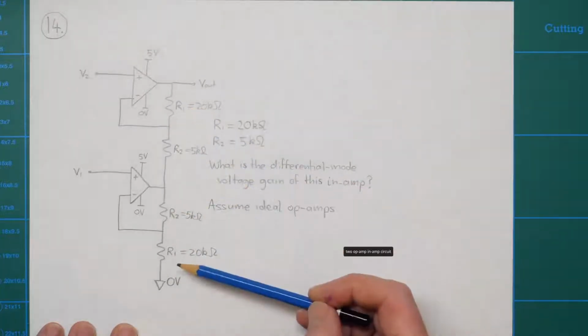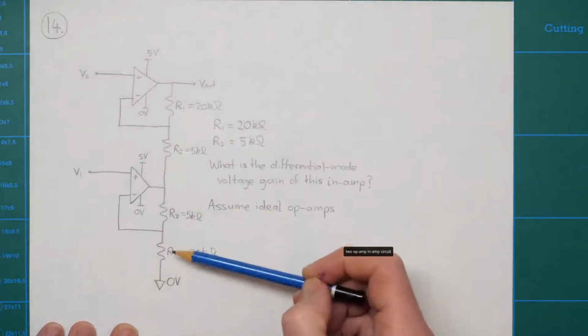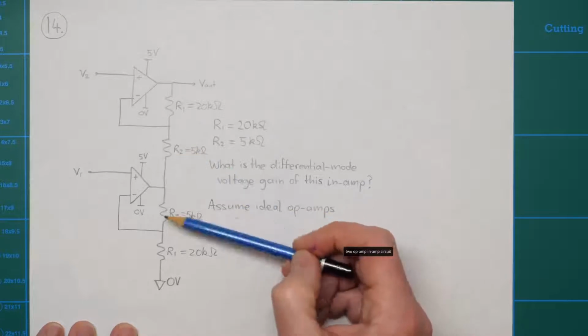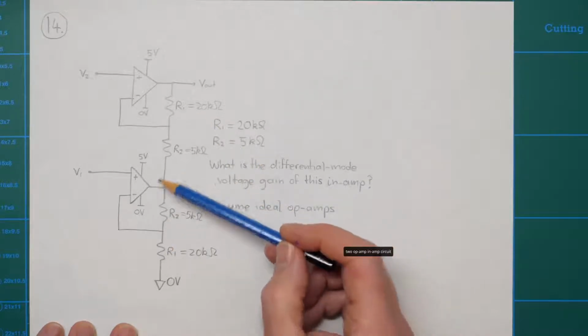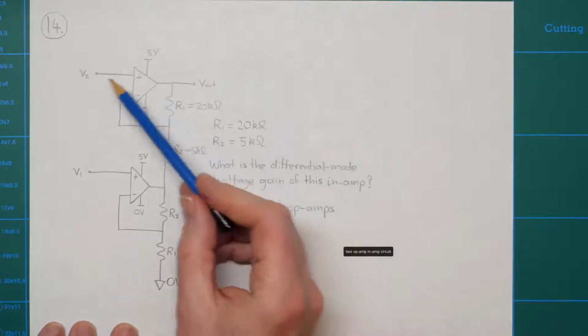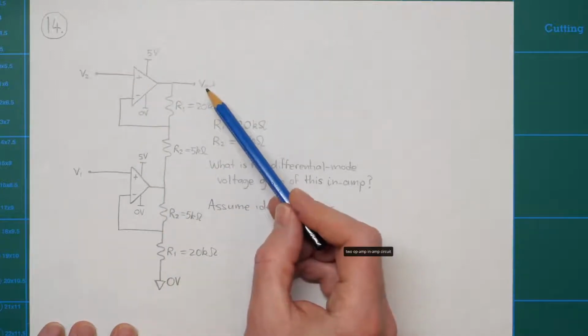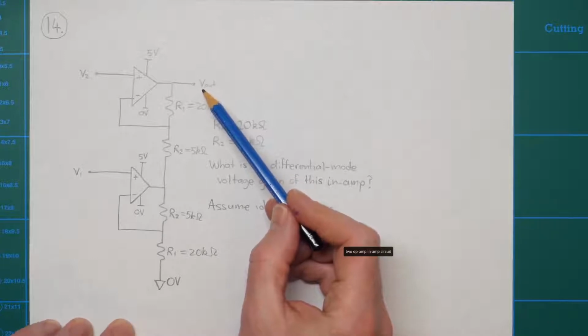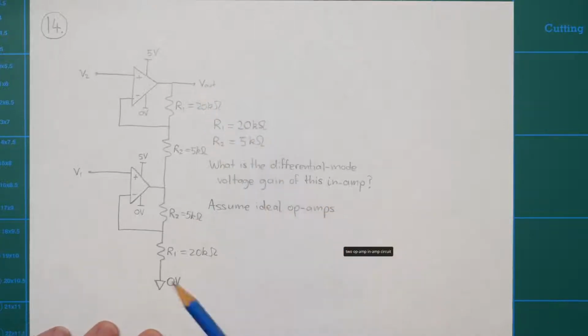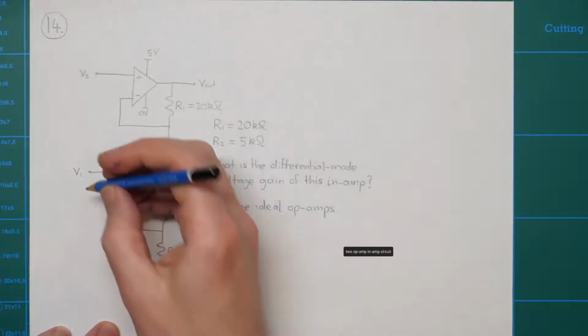These two resistors should be very close to being equal, and these two should be very close to being equal. If you don't achieve good resistor matching, the performance of the in-amp is going to be degraded. You start getting common mode signal leaking through to the output, which will really degrade the performance, especially in a biopotential amplifying application.